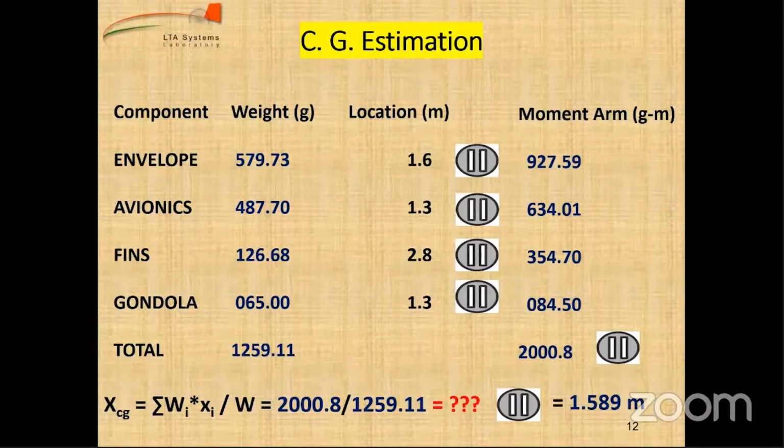And normally, where would you like to keep this ballast? At what location, what point in the airship would you like to keep the ballast? In the gondola? No, that really wouldn't change the CG much. Sir, we will decide the location of the ballast according to the adjustment we require in the CG. Like if you have to move it forward, then we will do the required changes.